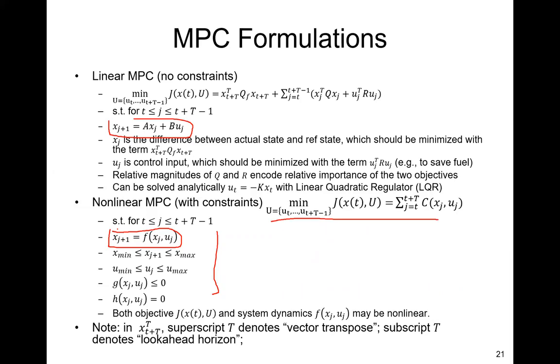It can be very hard to obtain for complex systems, like a very complex vehicle with road interaction, which is complex. The road may have snow or ice on it, so the tire friction may be different. So the system model may not be very accurate. That's the key challenge for MPC: you need a model that's accurate enough so that the prediction is accurate enough, and at the same time, it must be computationally efficient.